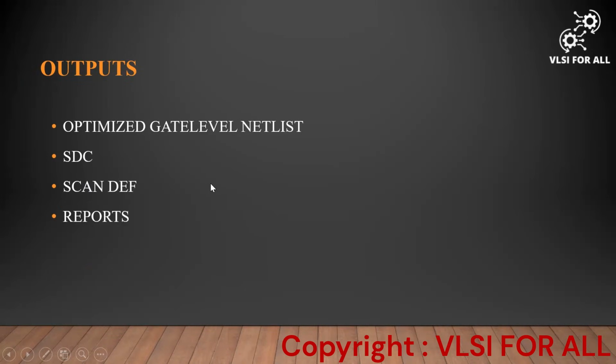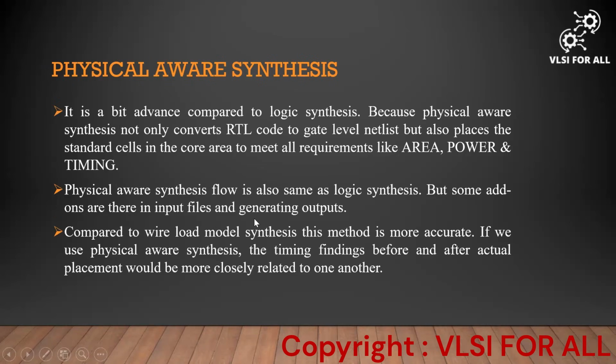Now we'll go for physical aware synthesis. Physical aware synthesis is a bit advanced compared to logic synthesis. What is the major difference between logic synthesis and physical aware synthesis? We all have some doubt like that. Basically, the difference is that in physical aware synthesis, the tool places all the standard cells in the core area, which does not happen in logic synthesis. That is the major difference between logic synthesis and physical aware synthesis.